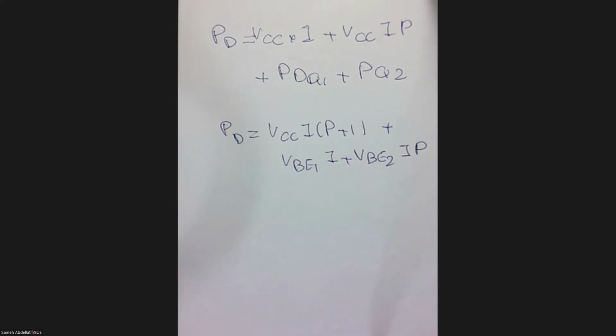This is simply because you don't need to turn on your transistor or your CMOS transistor sensor all the time. You have to have two modes of operation. What we call an active mode, during which you are doing your sensing process, and the other is what we can call a sleep mode, where your sensor is turned off, or ideally turned off, in order to minimize the energy consumption.